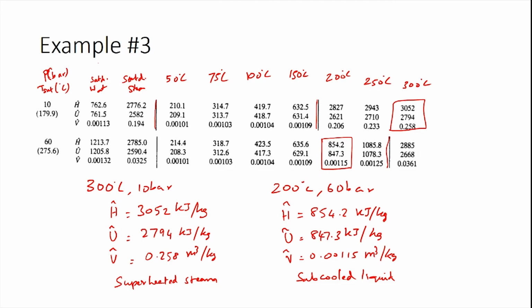So, this indicates that the specific volume of steam, which is much higher than the specific volume of liquid water, influences the change in enthalpy. So, this is an aspect which we need to understand and which we can appreciate directly by looking at these values from the steam tables. Let us perform the calculations for finding the difference, so that we will get the answers required by the problem.